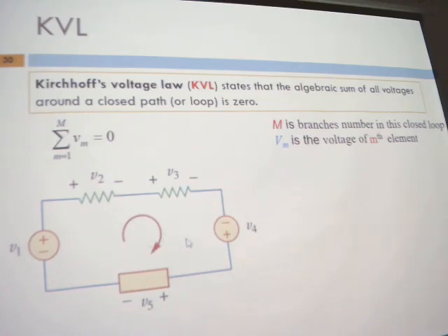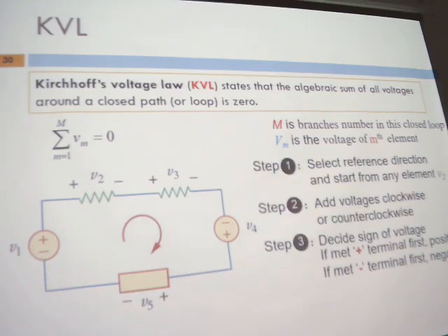Okay, let's look at the simple example. This one is the figure we showed before. Okay, we say we cannot have any use for KCL law, so we will use KVL law. So now I just showed you some steps to solve a problem. Okay, so for this case, on the first step, we need to select a reference direction and start from any element. Here I select the clockwise, and you also can select counterclockwise as well.